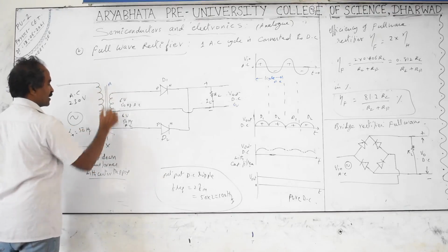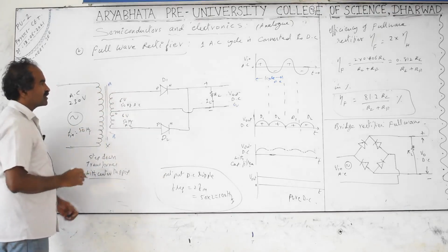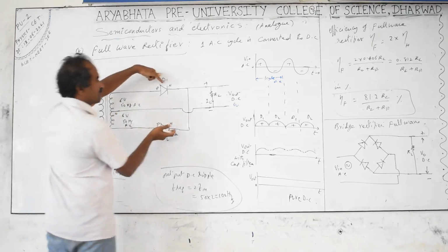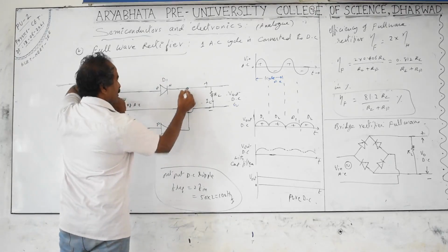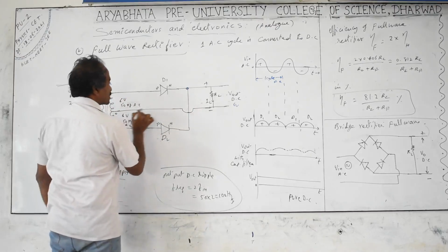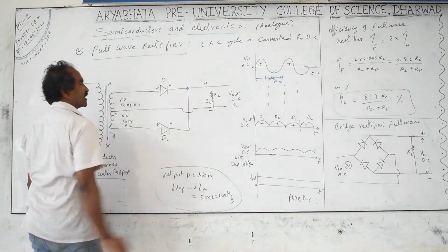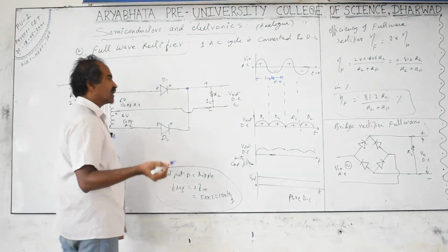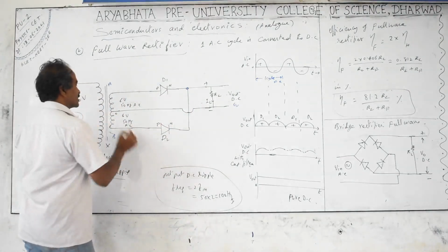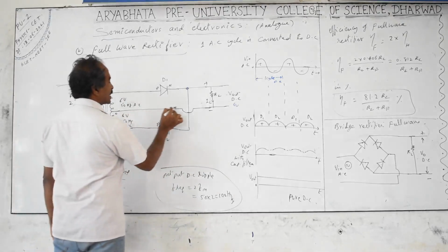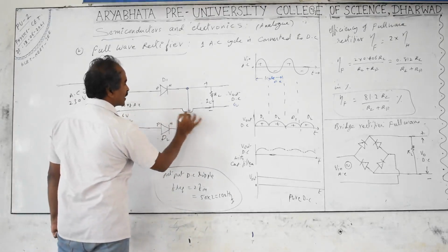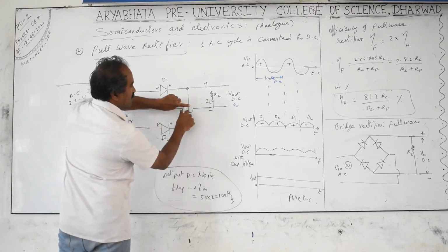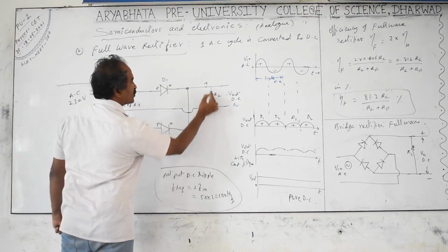And at the end points A and B, the polarities will change between plus and minus. Two diodes are connected at the extreme ends in parallel, same direction, and joined here. In the center tapping connection, the straight lines you are taking are nothing but connecting wires of more thickness, which carry more current with less resistance. Here the center tapping wire is taken with a loop. Loop indicates no connection to this wire, it is jumping over it, no touching. And it is connected to these output terminals.